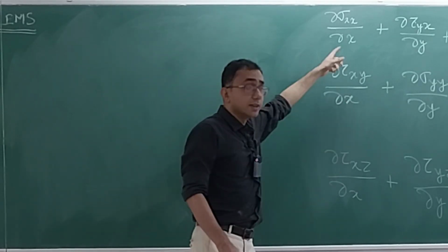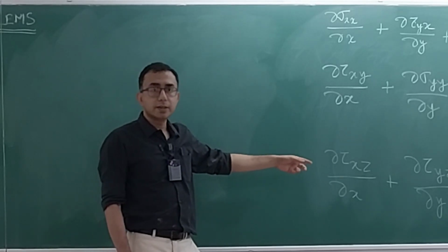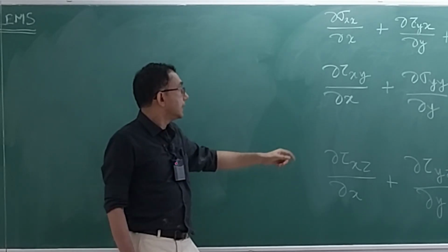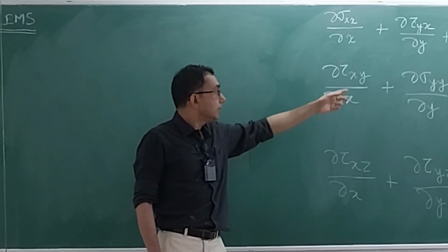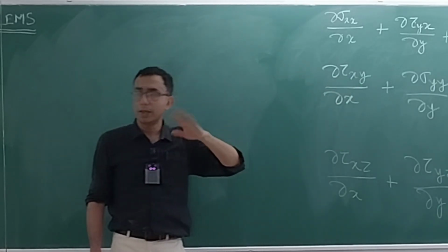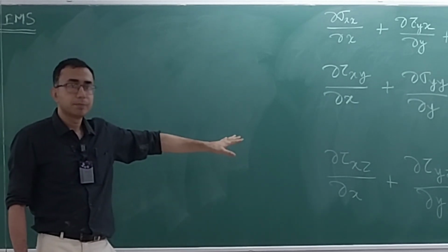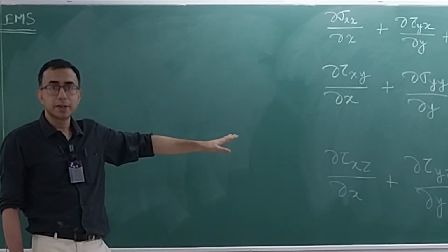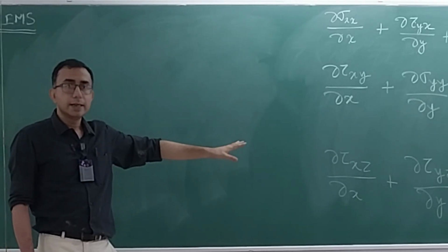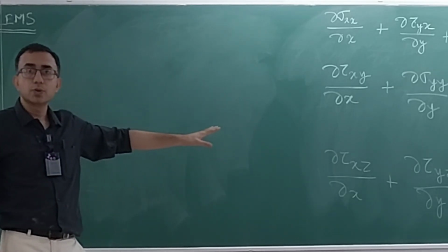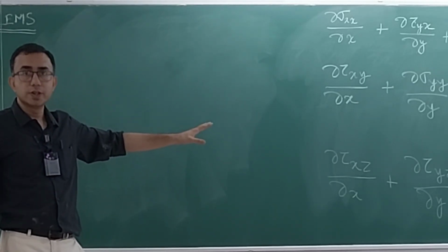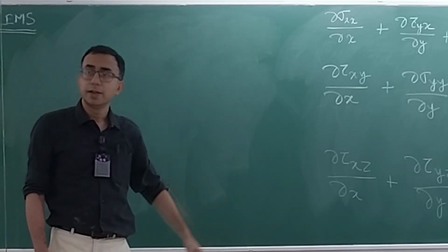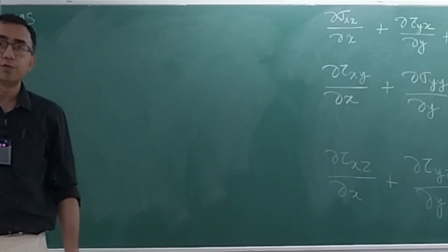You see, there are three equations here. How many unknown components are there? We will take it as given that tau yx is equal to tau xy, and all those things we will allow. That much we'll allow. So how many unknowns are there? 6. How many equations are there? Can you solve them? No matter how much mathematics you do, you will not be able to solve them. So in mathematical parlance, this is a system of equations which is not yet closed. So we have to close the system of equations. How can we do it? You have had a similar sort of discussion in fluid mechanics.